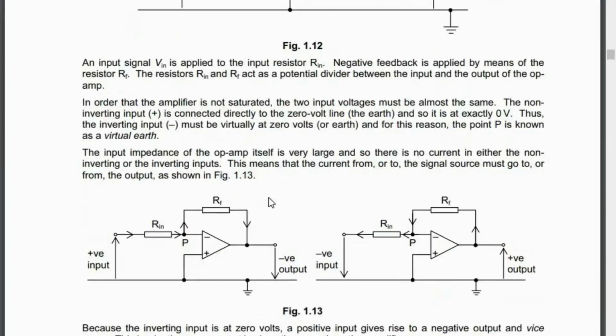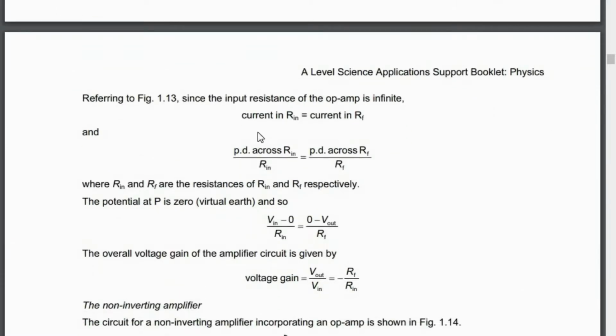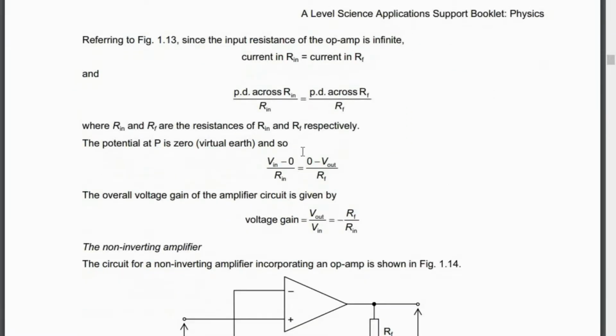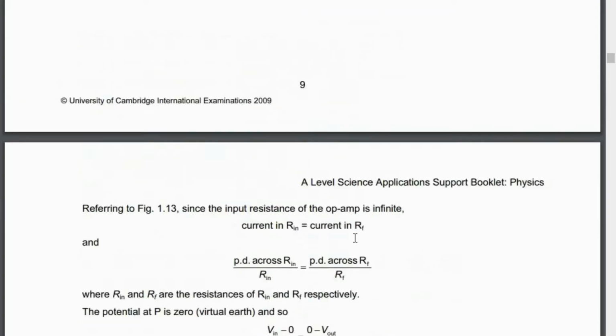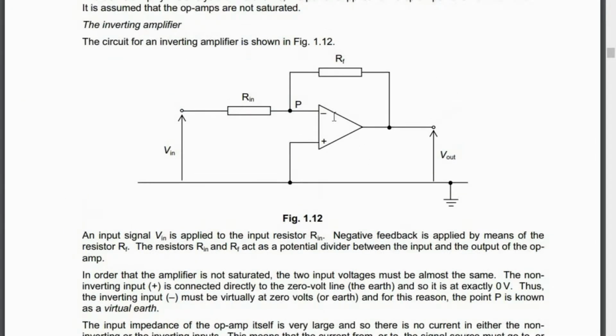Okay? So I'll be skipping through these points. I'll expect you guys to read through this. Okay? How do we get this? And eventually it's just two lines of series resistances. So this is the important thing. Okay? Voltage gain is minus RF by RIN. So basically, why minus? Because inverting input. RF, resistance feedback, divided by resistance input. A ratio determines the gain of this.